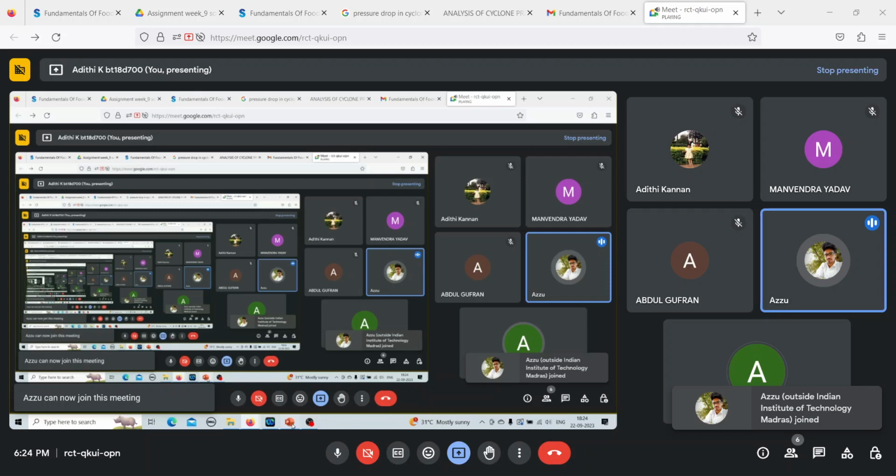such as the shell and leaf filter, where you have a huge shell and you have multiple leaves inside. You will send the feed inside the leaf, or you can send it outside in the shell also. So basically you will send it in one direction, and after filtration you will collect the filtrate outside. You have shell and leaf filter. You have automatic belt filters, where you will send your slurry through a belt, it will filter out, you will get the filtrate collected down, and then later on you will have to scrape out the cake.